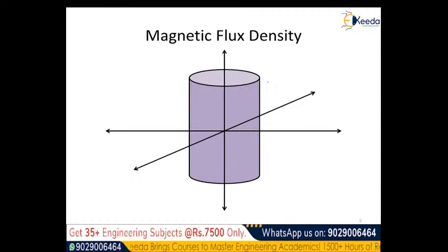Now in continuation to this situation, the conductivity value is provided for this material here. See, the conductivity is given by sigma is equal to 10 to the power 6 multiplied by the bracket where we have 1 plus 10 to the power 6 rho square, and this is represented in Siemens per meter. Now as the body of this conductor is cylindrical in shape, the convenience will be to have things represented by the cylindrical components here. We have learned the cylindrical coordinate system, and